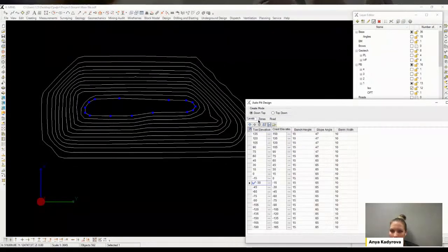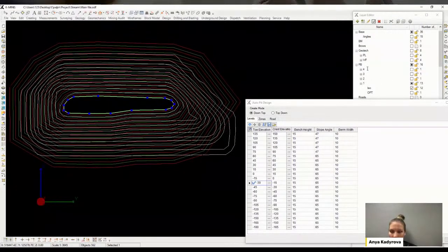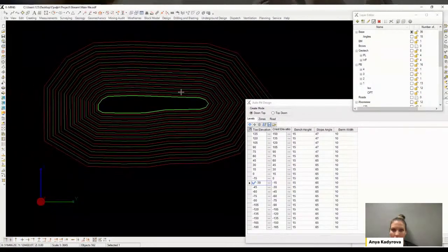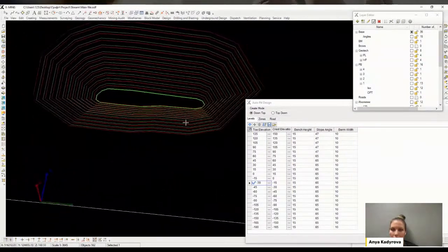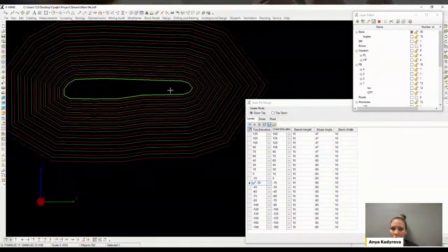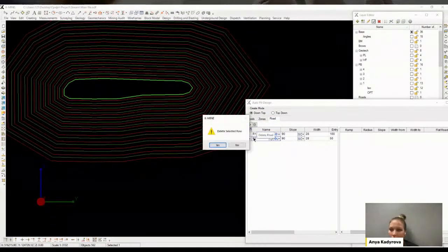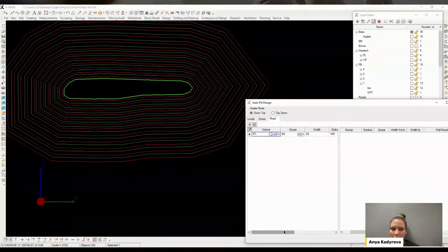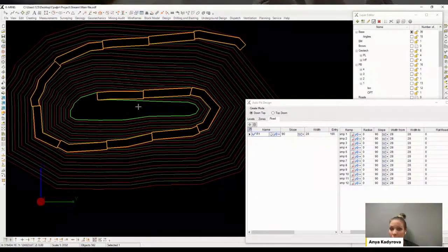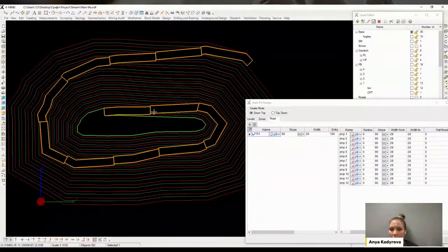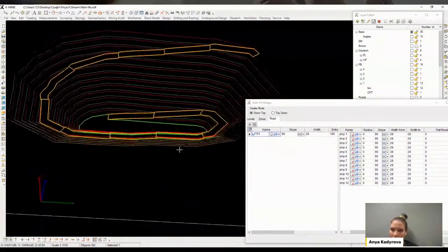So let's add a road to build it automatically from bottom to top. As you can see, it was created from the lower horizon to the upper one in a matter of seconds. It's not uncommon to have to adjust the road to different conditions. For example, to change the location of the road, you can change the point of its beginning, complete its construction at the end of any exit, or change the width of the exit part on one or on two sides.